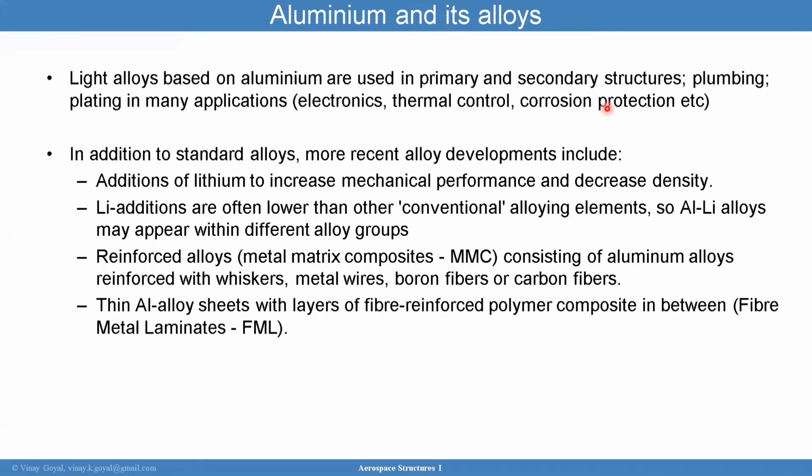So a lot of alloys are based on aluminum and they're used in primary and secondary structures, in the plumbing particularly, and plating in many applications. That'll be electronics, thermal control, corrosion protection, and so forth. In addition to standard alloy, more recent alloy developments include the addition of lithium to increase mechanical performance and decrease density. Lithium additions are often lower than other conventional alloying elements. So aluminum lithium alloys may appear